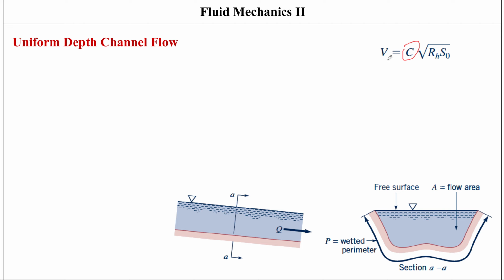Okay, so from this Chezy equation, then Manning, who was another engineer back in 1800s, he developed a more modified equation on the basis of this to more accurately then describe velocity in terms of the hydraulic radius, the slope of the bottom, and this variable n, or constant n, which takes into account the surface material of the channel as well, because that is something that is not being accounted for here.